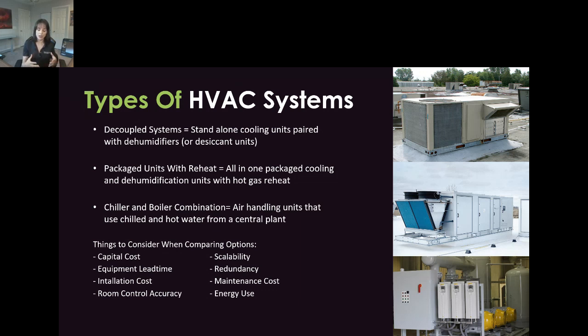So that air, once it is cooled and dehumidified, can then be brought back up to appropriate room space temperatures and put back into your facility. So you're not overcooling a space because you're trying to do the dehumidification. These units are typically more expensive than the decoupled units, but you're going to have an engineered system that actually has tighter controls in your facility.